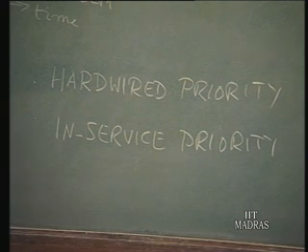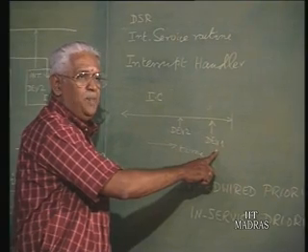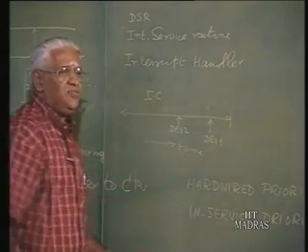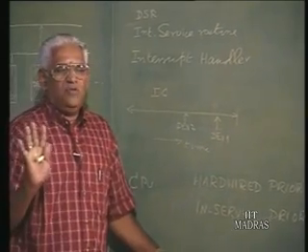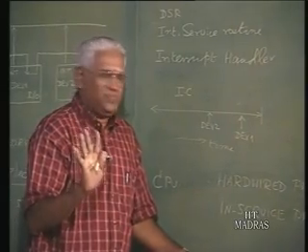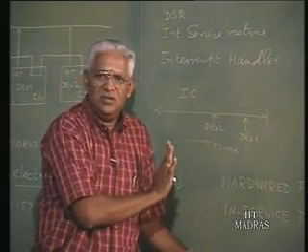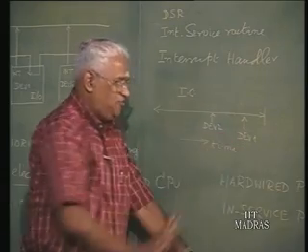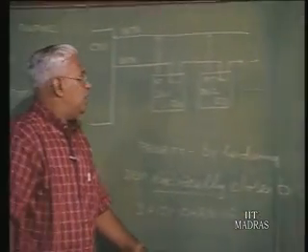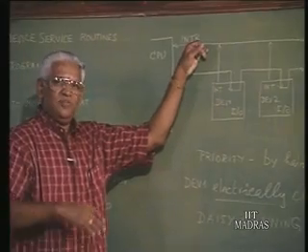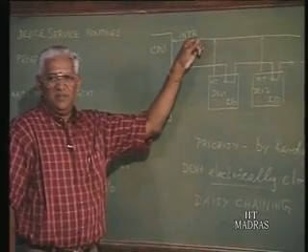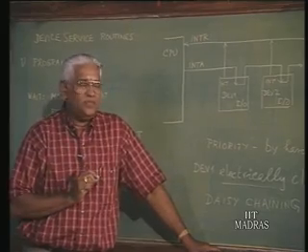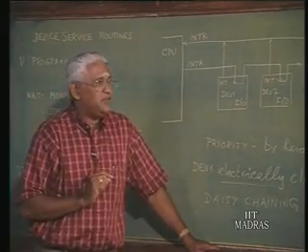Now, if we want device 1 service to be completed, what did we assume? We assumed that the device 1 service involves 5 instructions and so 5 instruction cycles. Now, throughout these 5 instruction cycles, if the interrupt itself is disabled, then device 1 service can be completed. So, that would be needed sometimes.